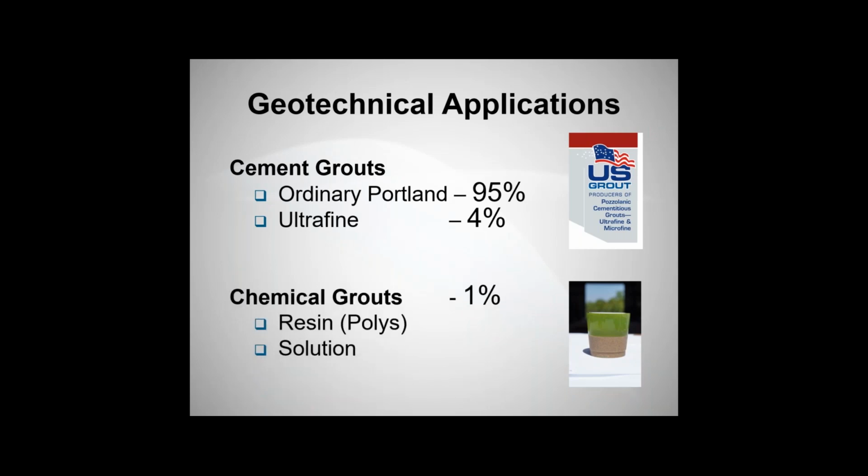And the other type of family within the grouts is the chemical grouts, also known as solution grouts. Those include the resins or the polyurethane grouts, also known as solution or chemically reactive grouts. Those only get used about 1% of the time.